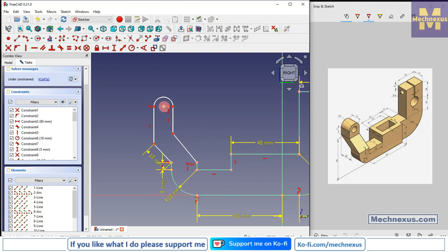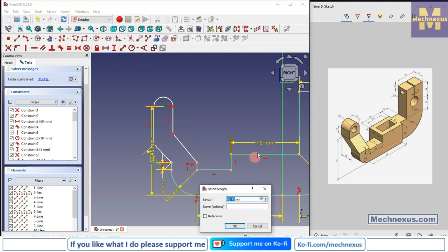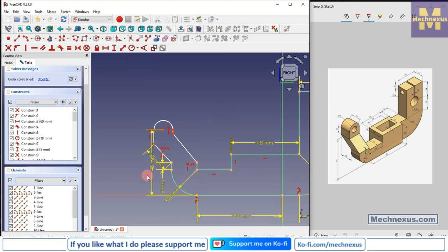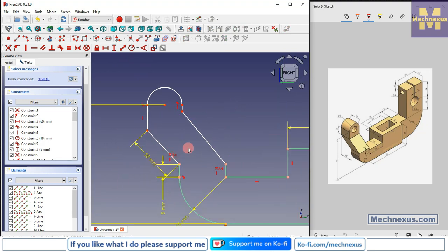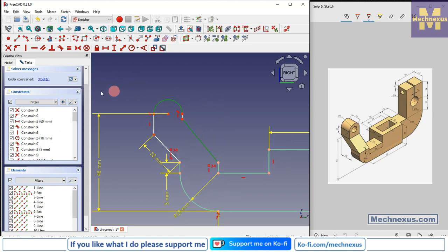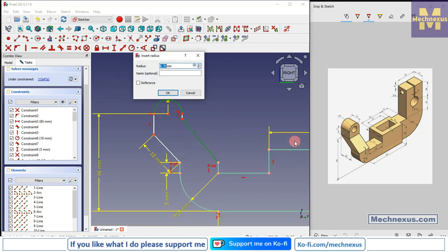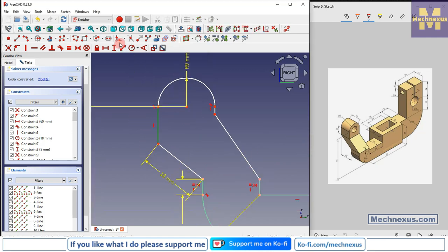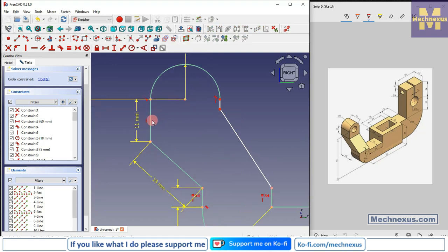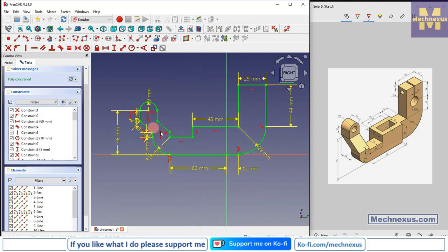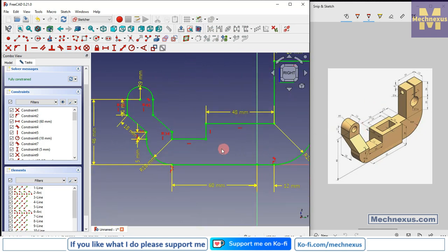Now select vertical dimension from this to this, it is 46. Now select this and we will not add the parallelity. We will constrain this radius, which is R9, and select this and add the vertical of 11 mm, and select this and edit it. So this is how our right profile will look like.